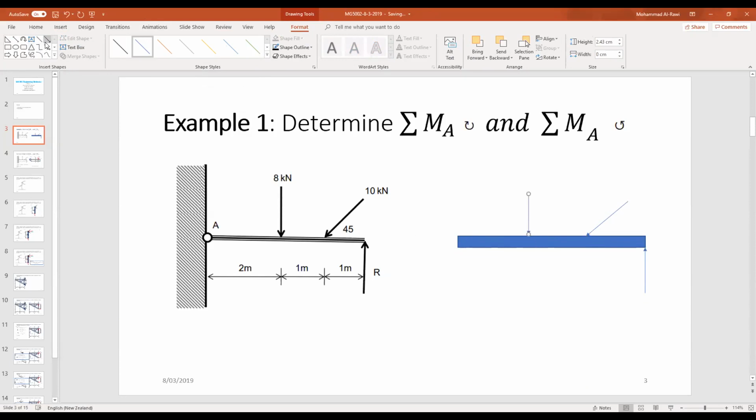There's also something very interesting: the support reaction at that end, which is a fixed support, indicates some interesting things which we need to explain more in the next topic next week. It actually indicates two supports. One is the fixed support we treated, but there is also a moment to prevent any rotation.